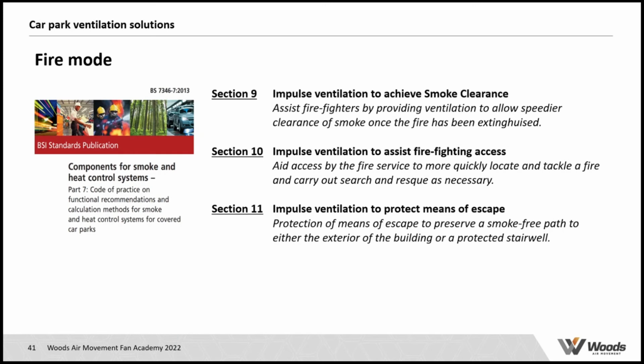And if the building regulations outline a minimum number of fire exits, then that's something you would design to as a structural engineer. And I find it particularly scary if you would do a design only relying on one escape route and then protected by mechanical means. So just so that you're aware that Section 11 is included in this document, but I would not put too much emphasis on it because, as I said, over the years I've been in the industry, I've never really seen a Section 11 design.